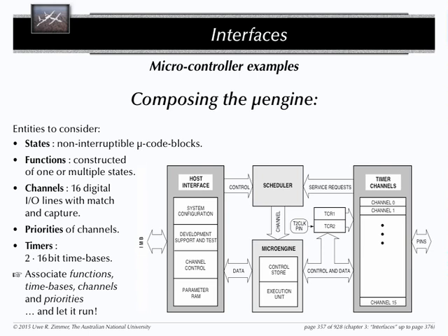I have only 2 time bases, so I cannot be too generous with the time bases and the functions. And I let go. And I have a system which handles my I/O here and gives me information on the other end in the dual-ported RAM to my CPU at the same time. And this can be calculated down to the last CPU cycle, how long that takes.